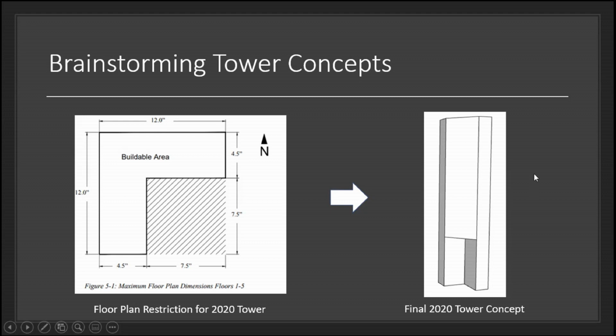One thing to note is that there are both some qualitative and quantitative analyses that we do when determining which tower concept to use. For example, being easy to construct is a more qualitative analysis that we do just by looking at the different designs. But we also model all of these designs in software such as SAP 2000 to determine structural performance, in terms of things like displacements and accelerations, since you can't as easily tell just by looking.